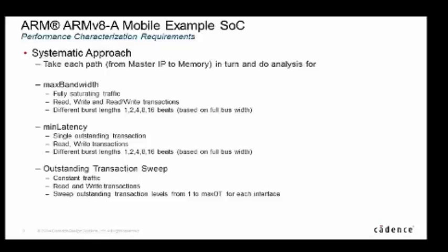It's not exactly the performance I'll get at all times. It won't be, right? It's a real complex environment. And the tool, through the visualization, helps you dramatically learn more quickly what the characteristics of an IP are, especially if it's a third-party IP, right? Do you get that in a data sheet? You don't. It will say peak bandwidth is 8 gig a second, but what's the actual real behavior when you put it in a system? And I think that's very hard to get out of a high-level model.